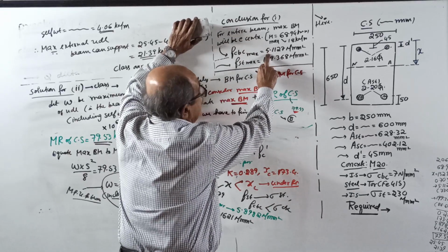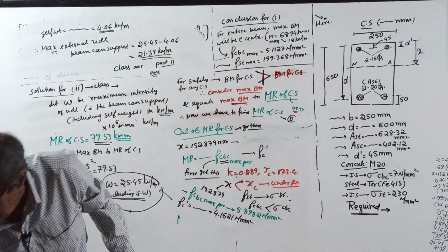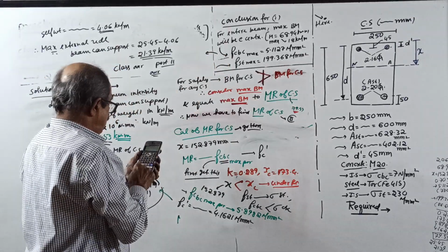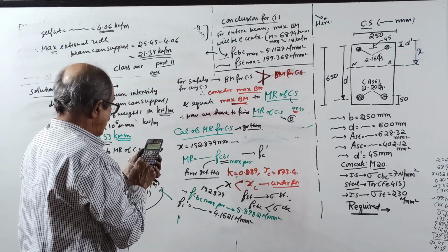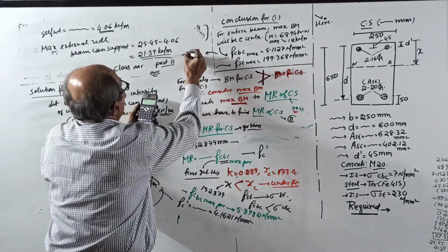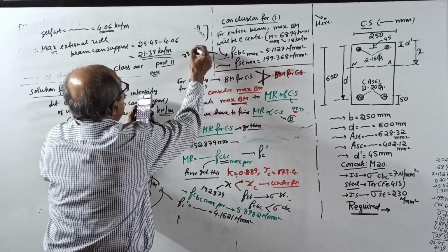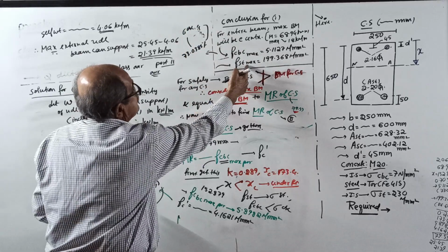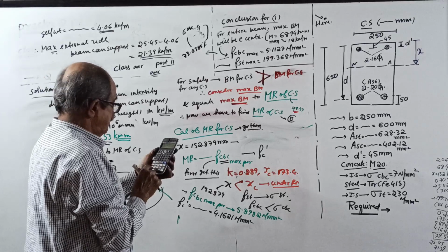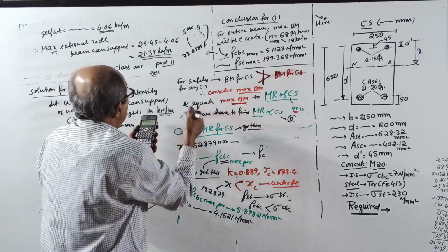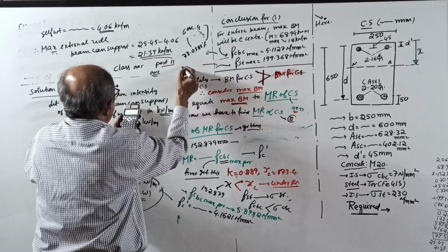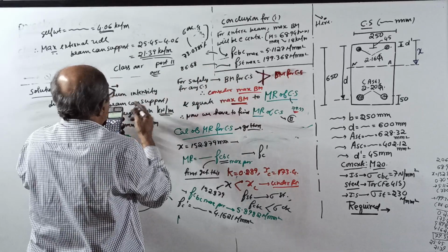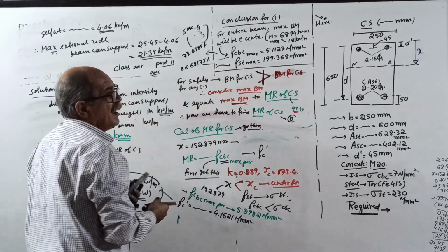Stress in concrete, see correctly, 5.1127. If you compare, 5.1127 divided by 7, it is 73.00385% of the limit of sigma CBC. Okay. Stress in steel we got 199.368 divided by 230. Stress in steel is 86.68173%. He will tell, so what?